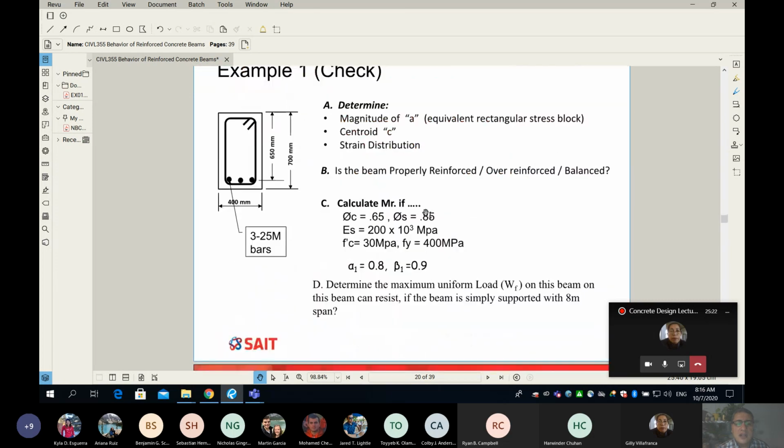However, a good understanding of beam behavior comes from doing the check. So in this class I will work through some examples with numbers so you understand the beam behavior and how we know whether a beam is going to fail in a tension mode, balanced mode or compression mode.